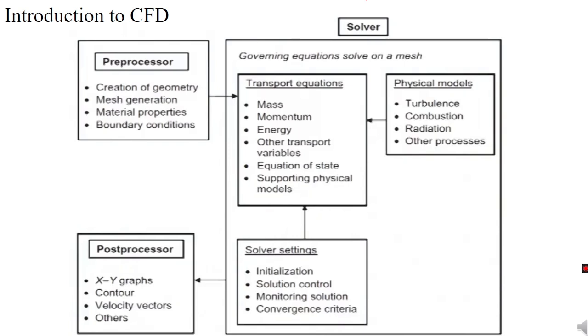So select the additional model if needed, like combustion, eddy dissipation model, or radiation model. Depending on the type of the physical model, we have to select the particular model, right?